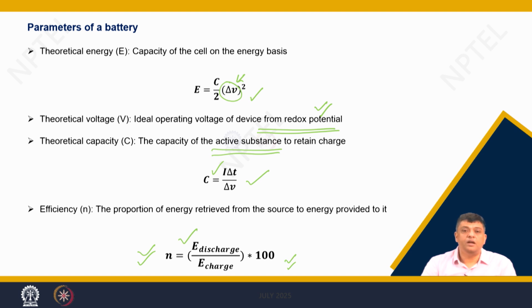But if you take lithium ion batteries to a state of deep discharge, then they cannot be revived easily. You have to pump in lot of energy, and when you do so, you degrade the materials, and hence the cycle life of the material comes down, and the overall lifespan of the battery then is significantly reduced.